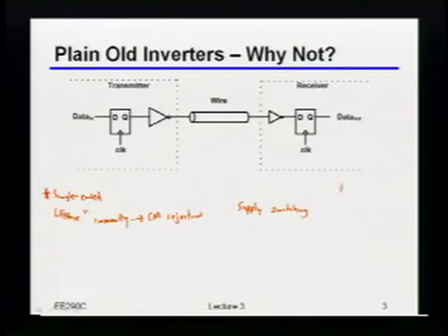You said something about the threshold. Now, is this a threshold of the devices? Yeah, so the transmitter and receiver are kind of far apart, so the PMOS-NMOS ratio might have some difference. Okay, so you said this is chip number 1, this is chip number 2, and of course those chips are, whatever, I don't know, 36 inches apart or whatever. In fact, although actually that probably doesn't matter that much, because it really matters when they were fabricated, or in fact where in the wafer they were.